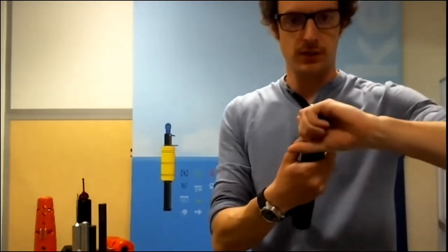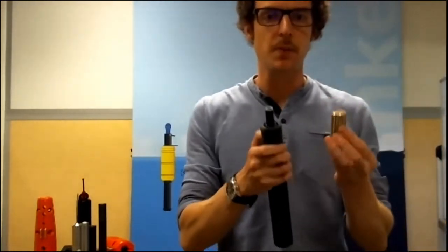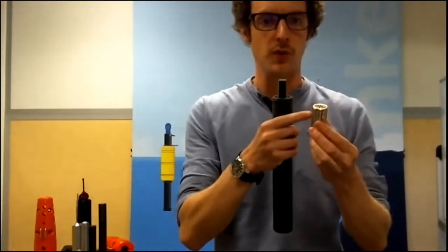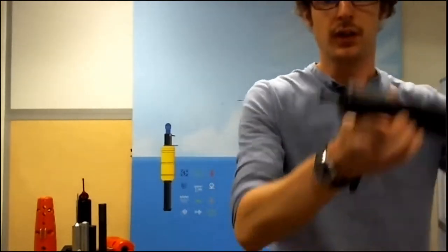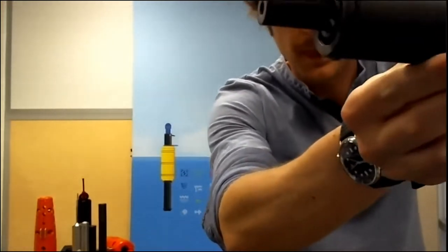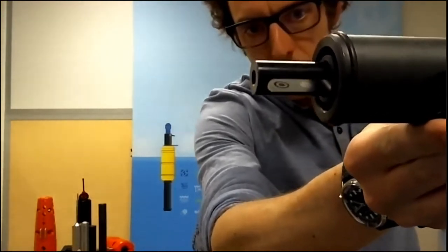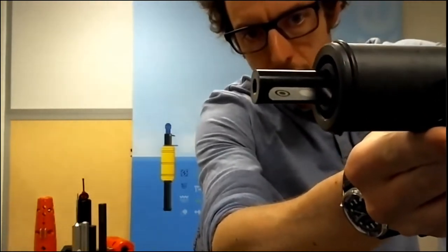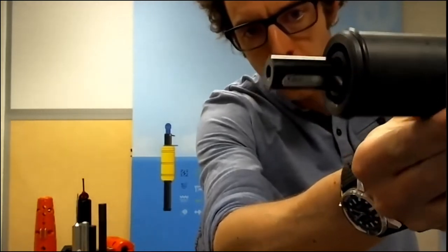Moreover, this cage is removable, which eases the maintenance of the instrument. So you can remove the cage and clean the cage with a metallic brush and clean with fresh water the cells. So I'm just showing you the cells. So here you can see, you have 2 types of measuring cells, one measuring the conductivity and one measuring the temperature, and you have one on each side.